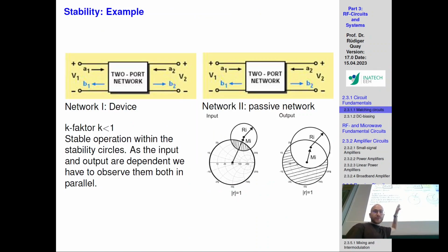So you can plot via this K factor, and knowing this information from the person who produces this technology, you can calculate impedance circles, at what frequency and what impedance points the performance will be stable. The device will be unconditionally stable.